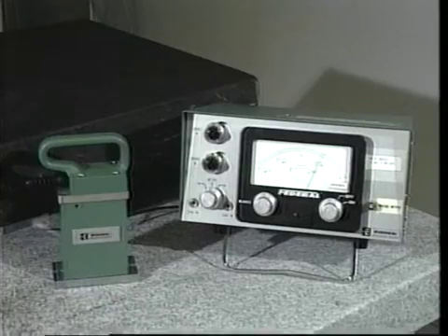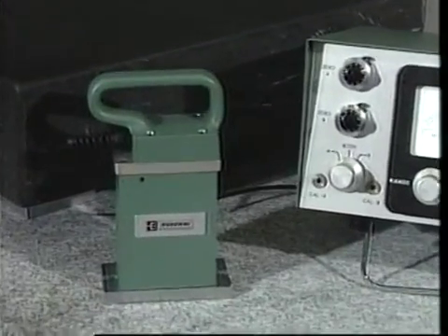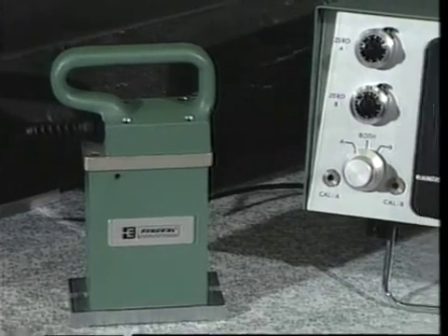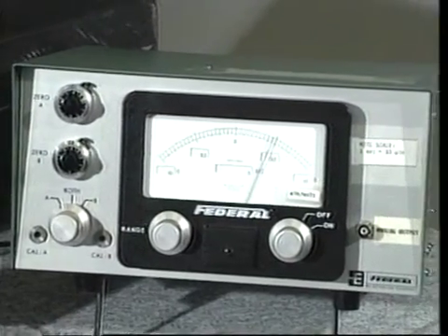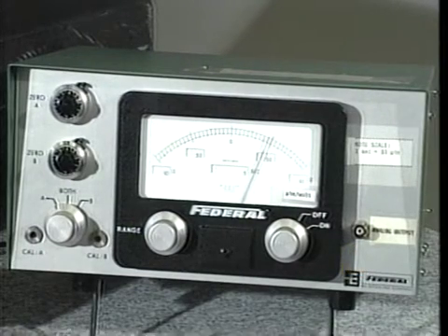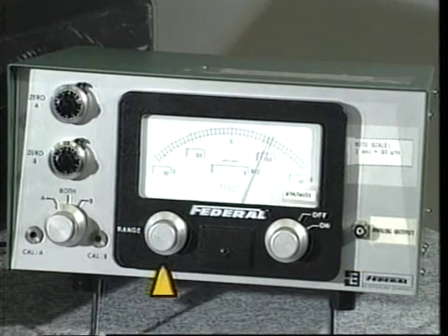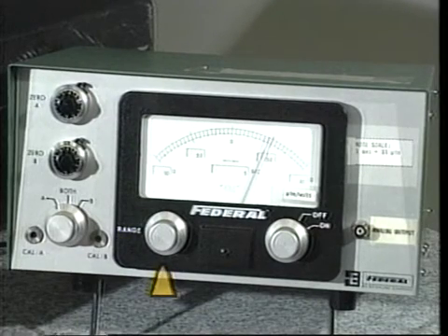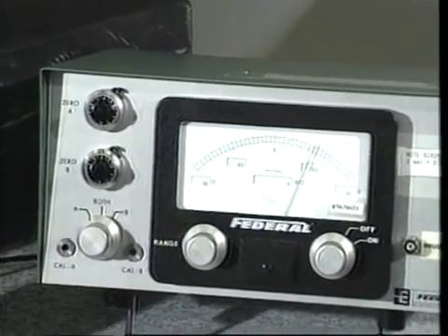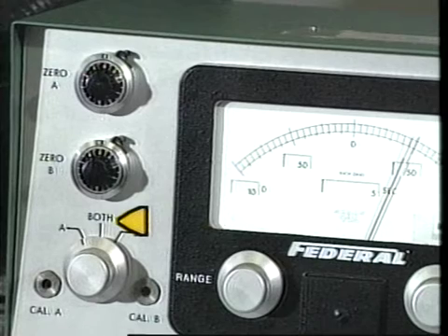As I stated earlier, two instruments are commonly used for measuring surface profiles, the electronic level and the autocollimator. In the case of the electronic level, a pendulum and a shaded pole inductor circuit are used to sense the tilt resulting from the height difference of the two sampled points. The measured angle can be read from the analog meter on the console or can be represented by the console's plus or minus 10 volt analog output signal. A choice of measurement ranges is available, with the largest range being plus or minus 1,000 arc seconds. The best resolution found on the smallest measurement range is a half an arc second. Note that this unit allows differential level operation.